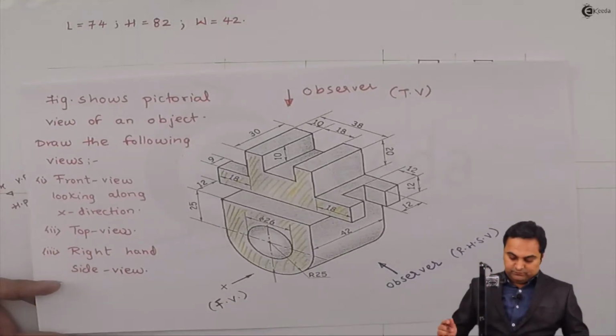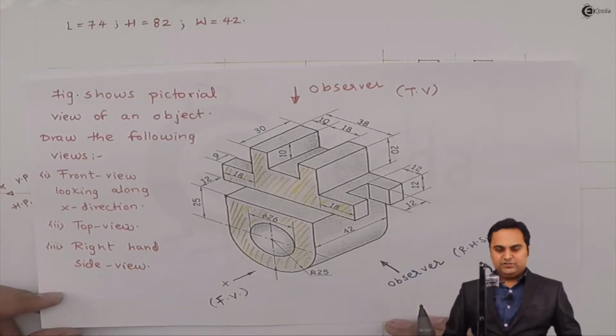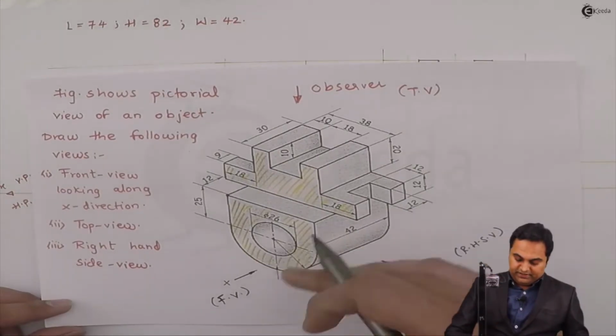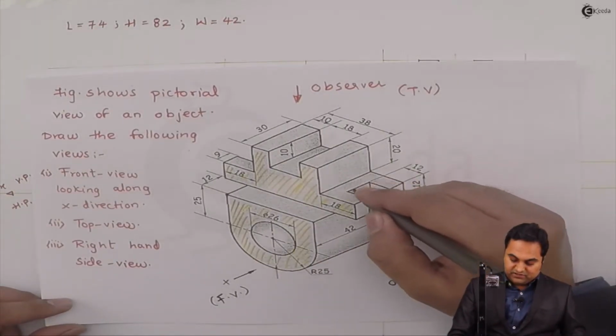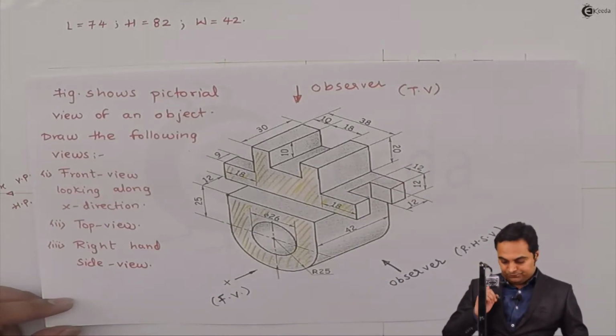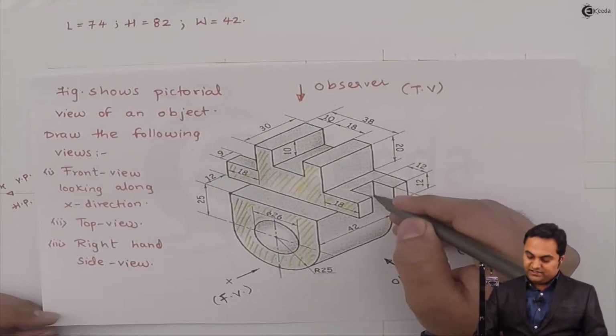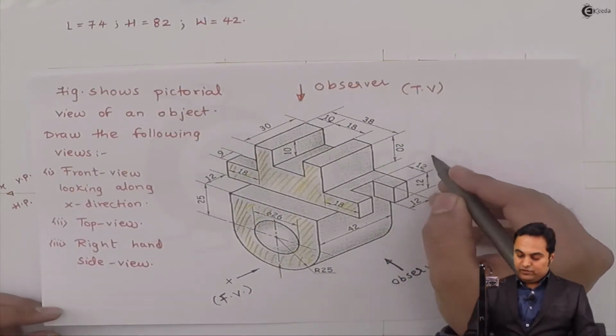Next, after that, I can see that the visible part is over, but inside this we have this line which is not seen from the front. It has to be hidden, and that line is through, as I see here. So it is having a length of 12 mm.